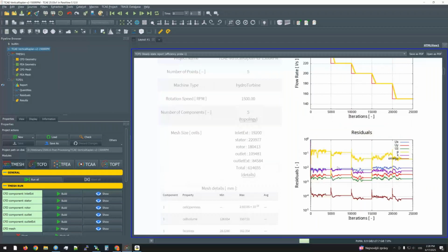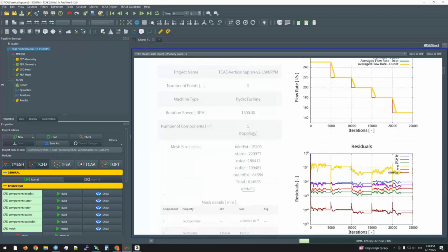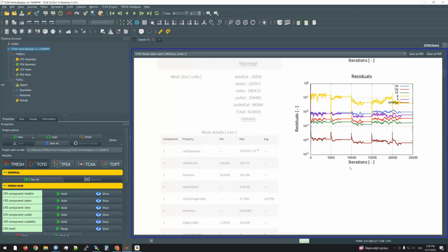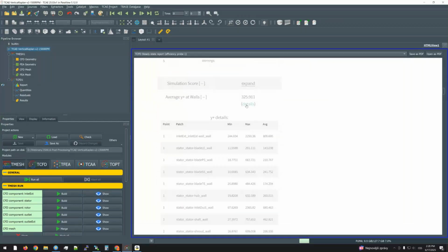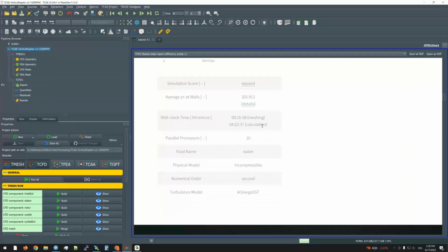So anytime you see something weird, graphs which are oscillating heavily or not going down, but mainly going up, I think you will directly see if the results are meaningful here, or if something very wrong happens during the simulation, like the simulation diverges or any other stuff. So this is the first view, which tells you, okay, if the simulation is okay or not. Yeah, you can go for analyze if, for example, your y plus goals and other parameters are okay.